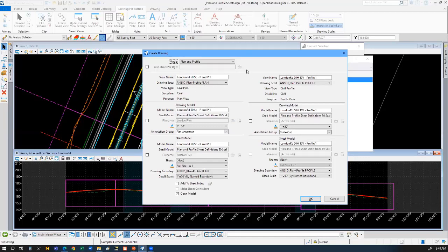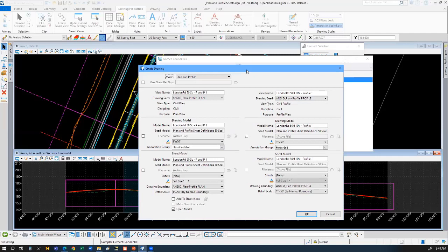And what I would get is ANSI D sheets that were drawn at basically 1 in 50, but scaled at 1 in 20 or 1 in 10. So everything would be off. All the annotations would be off, and so on and so forth.